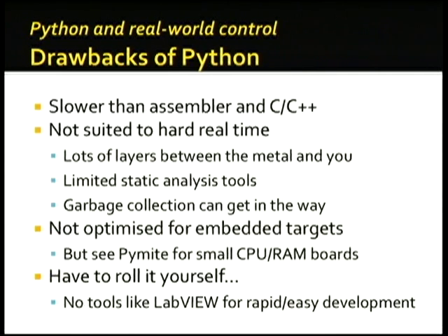Slower to possibly perform, but not slower to write and actually get to a working prototype. It's often not suited to hard real-time, certainly not when you're down into the microseconds, the nanoseconds, the femtoseconds. There's lots of layers between the actual electronics and the Python interpreter. Limited static analysis tools means that you sometimes don't get the level of checking that you want before you ship your pacemaker out. And the garbage collection can get in the way, as it does with any garbage collected system.